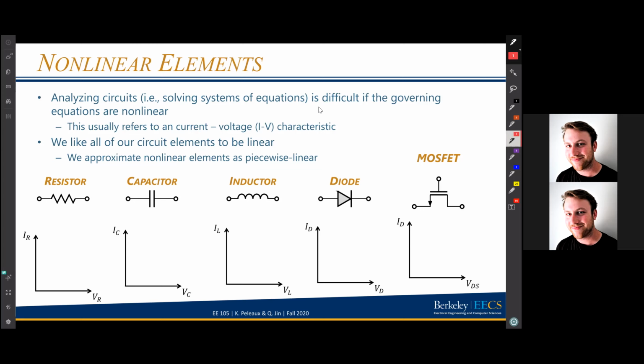So for a resistor, we have a pretty basic relationship, right? It's a linear relationship. The IV characteristic looks like a straight line, where the slope of this line is actually 1 over the resistance, right? Because the resistance relates the voltage and current, we can say that that slope, the current over the voltage, will give us 1 over the resistance. So it's like a conductance.